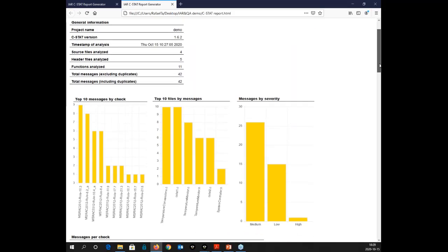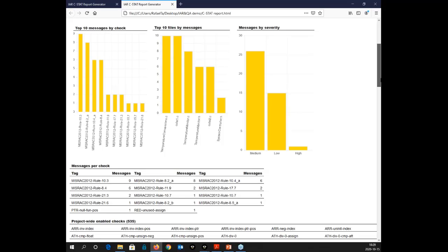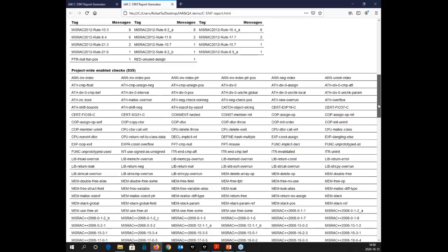What would also appear here, and that happens sometimes, is that in order to get rid of a specific message that gets triggered, you end up suppressing it. So that's not the right way to solve it, but if you do that, it will be documented here too. So what I'm saying is that to be compliant with MISRA-C, if you suppress a specific warning, you need to make sure that you document that you tested it, that it's working according to what it's specified. Then you can still be compliant with MISRA-C if you end up needing to disable one check or another.